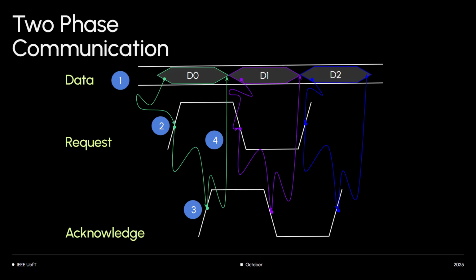So it's the request, trigger, the acknowledge. So the request is triggered by the master or sender, and then the acknowledge is triggered by the receiver. Okay. Does that make sense? Yeah. Right. The only rule is, if the sender is saying 0 to 1 is an event, if it did 0 to 1, your receiver should also do a 0 to 1. Okay. So the type of event needs to be the same. If this is saying hello, this should say hi. If this is saying hello, you shouldn't say bonjour in French or something like that. You need to make sure that you speak the same language, right? So that's what the type of events mean.